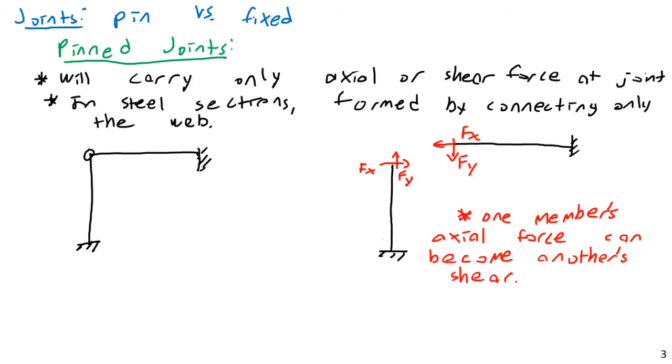Do be aware, usually when you have a circle like this in a joint, this refers to a pin joint rather than a roller joint. And the reason for this is if this were only a roller joint, that really wouldn't make sense for an internal joint. How would you have just force in one direction at a joint? Why would anyone build something like that? That really doesn't make much sense. Your frame would basically be collapsed at that point.